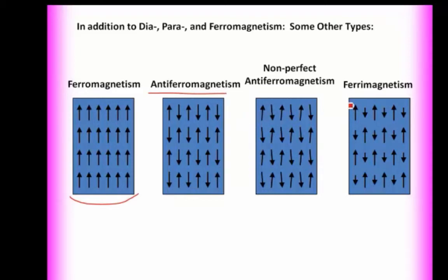There's one more, and that is you have something that's close to the anti-ferromagnetism, where one direction is favored over the other. So you end up having an M. See, here you have an M equals 0. You end up having an M because this one's bigger than this one. So that's called ferrimagnetism. Now, I hate to tell you, but these materials are extremely important technologically. And in fact, this is used in disk storage, partly because you can switch this very, very fast.